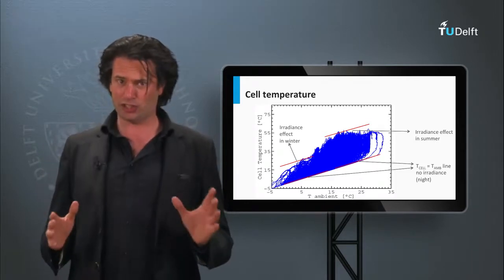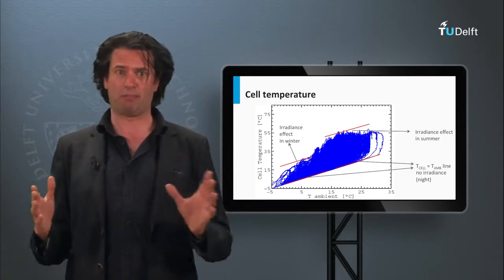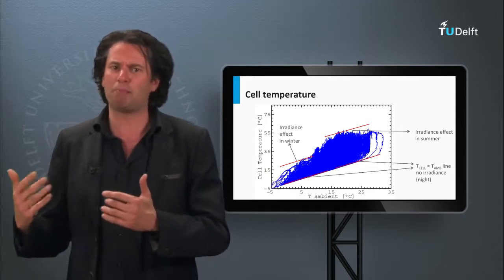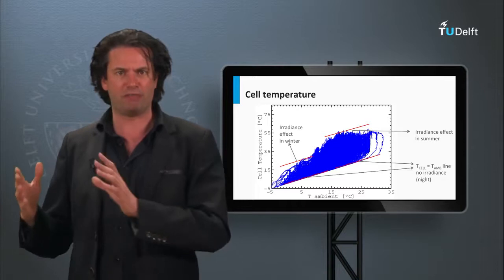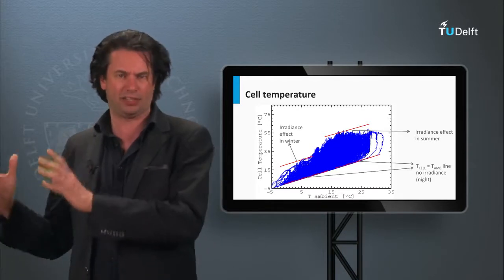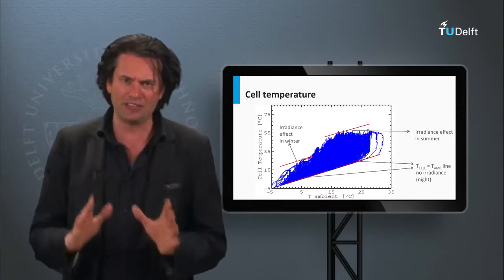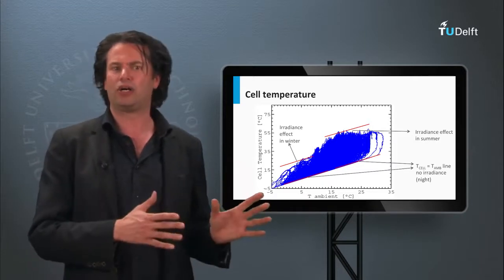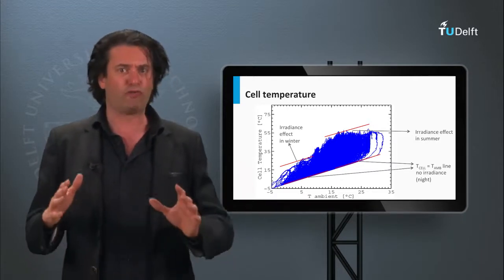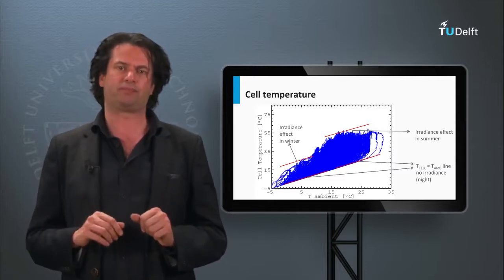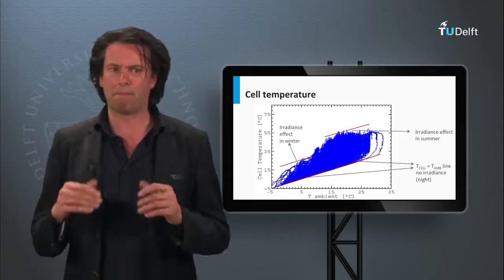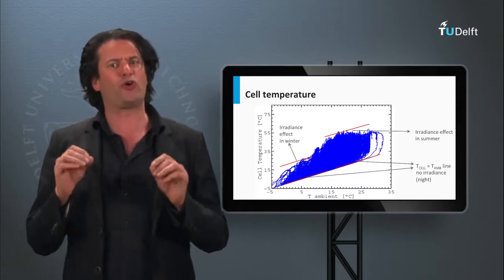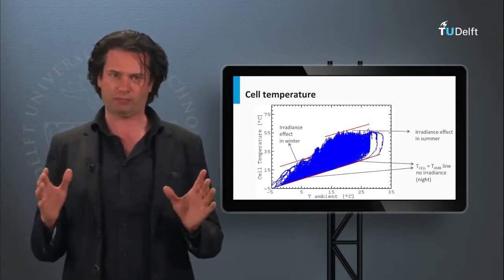This means that in summer, although the sun is shining more, the module is performing worse due to the temperature effects that bring down the PV output at a high cell temperature. In winter, the detrimental temperature effects are far less, although the irradiance levels also fall severely in winter. This means that the best ambient conditions for your PV module would be a cold day with plenty of sun.